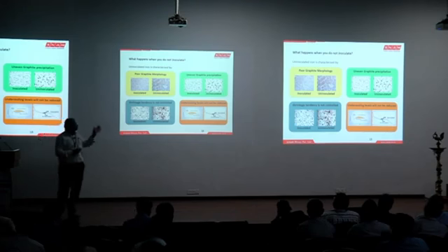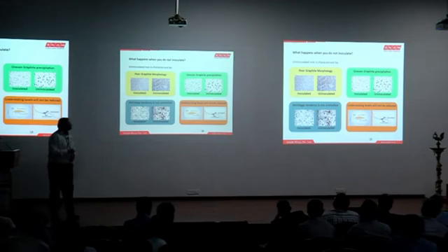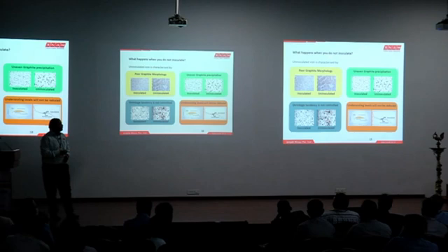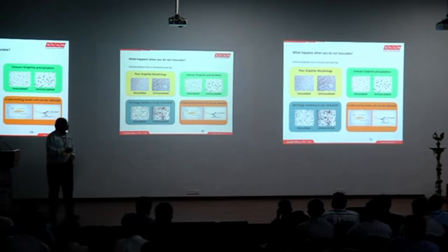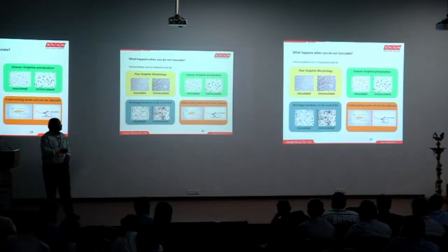So inoculation is added to ensure that you get uniformity, that means non-defect structures throughout the castings, at least bare minimum. So if you don't inoculate, you will be getting uninoculated, that means undercooled graphite, not 100%, but maybe at all the hotspot locations or fast cooling locations, which might be a working location of the final functionality. And uneven graphite precipitation. So that means you might be having the same amount of carbon here and here, but the amount of nodules formed in case of ductile iron may vary.